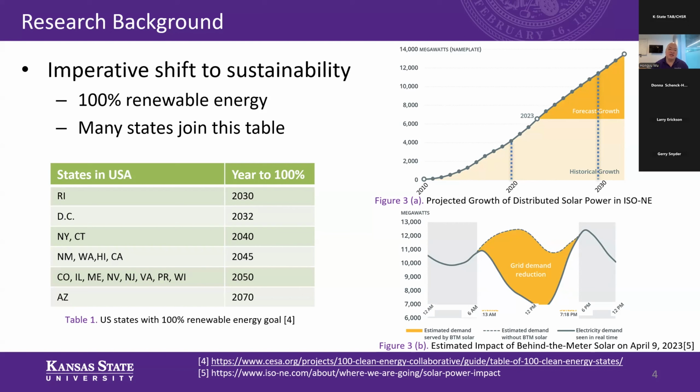The behind-the-meter PV drives demand for grid electricity to a record low when the solar energy reaches its peak. As some of you may know, this phenomenon is referred to as the duck curve, because a line charting the grid demand on such a day resembles a sitting duck. The duck curve tends to occur during spring in ISO New England. This is typically when the electricity demand is lowest and the temperatures are mild.